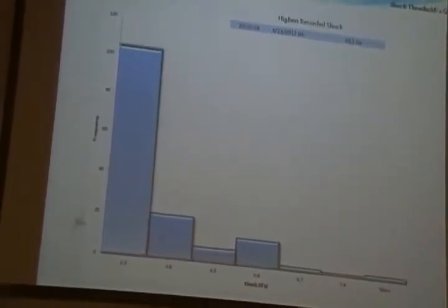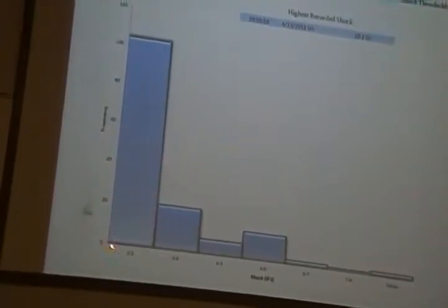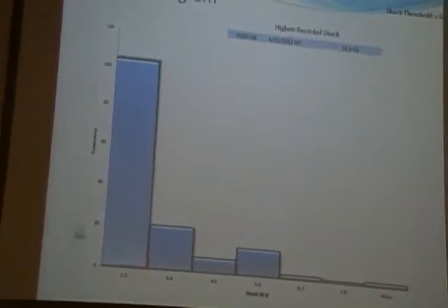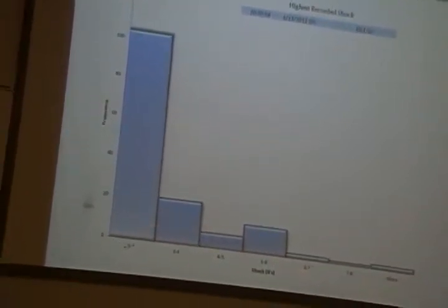So for shock, using the LCD, we set the threshold to be 2 Gs because we want to quantify the shipping environment and want to be able to make sense of it. As you can see, we created a histogram for shock. It recorded a lot of shock from 2 to 3 Gs. And we assume this is because of automatic handling and sorting equipment.